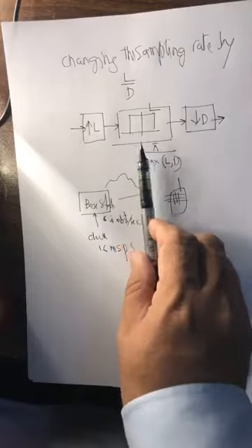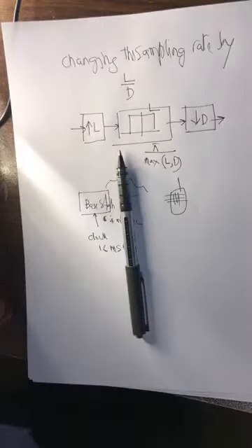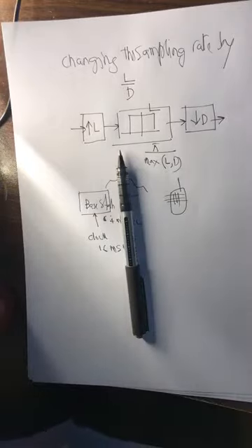So for the MATLAB FIR1 command, I want this lab to be heavily tilted towards interpolation, decimation and polyphase decomposition, so that you understand all the intricacies. Dr. Ali and I will discuss that. You take a signal, insert zeros, and plot the spectrum. You take a signal, plot the spectrum, pass it through a decimation filter, and plot the spectrum again to visualize that now you have thrown away part of the spectrum, and only then you decimate.